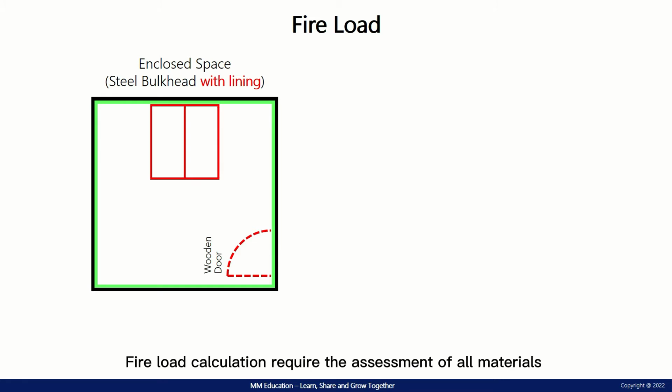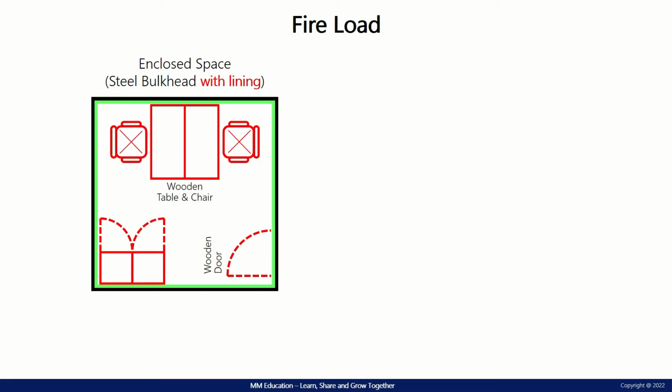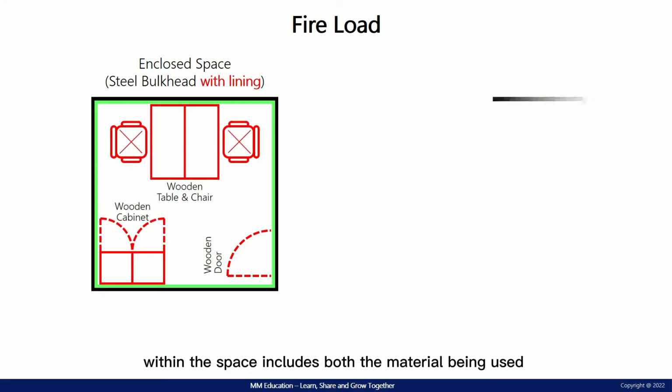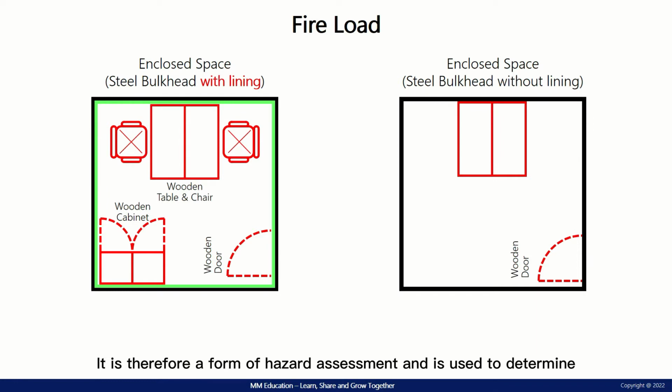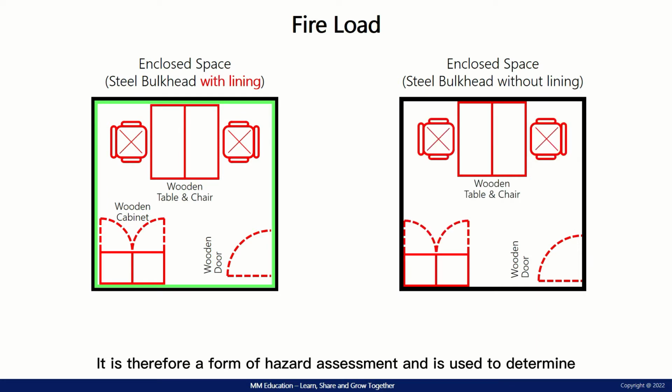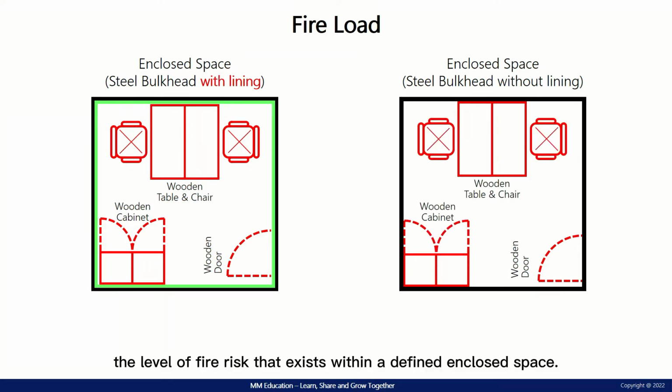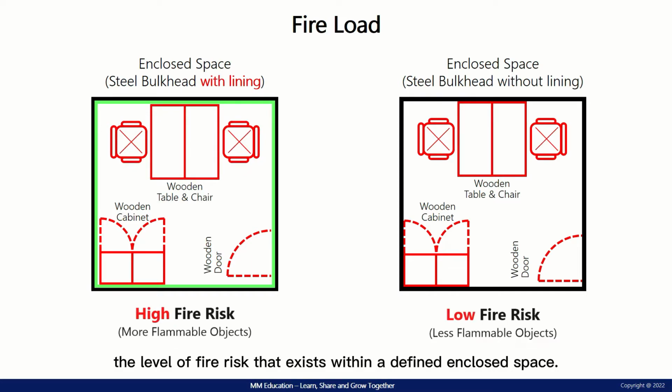Fire load calculation requires the assessment of all materials within the space, including both the material being used in the structure and flammable objects or substances that may be stored in it. It is therefore a form of hazard assessment and is used to determine the level of fire risk that exists within a defined enclosed space.